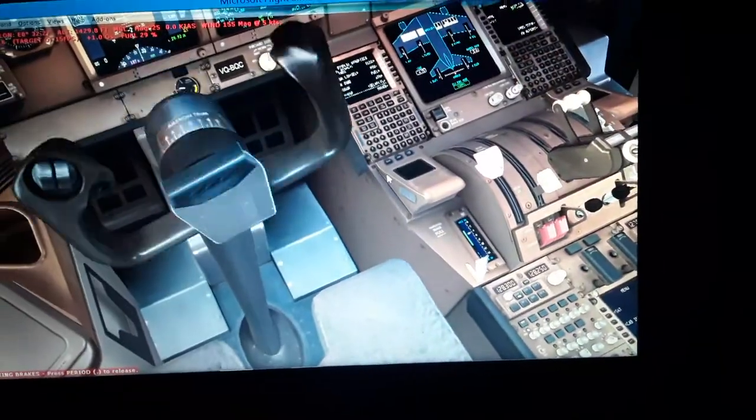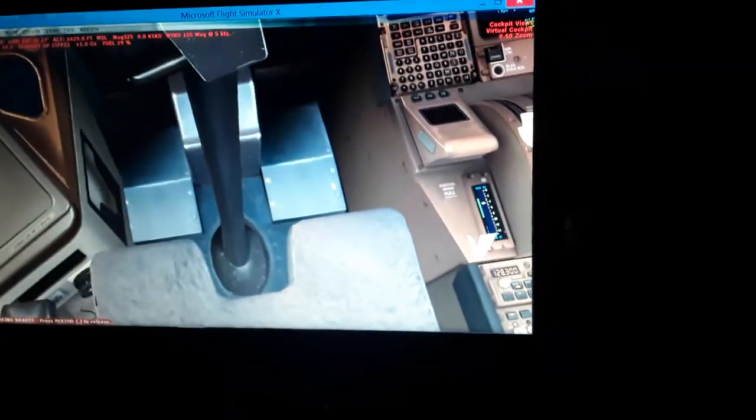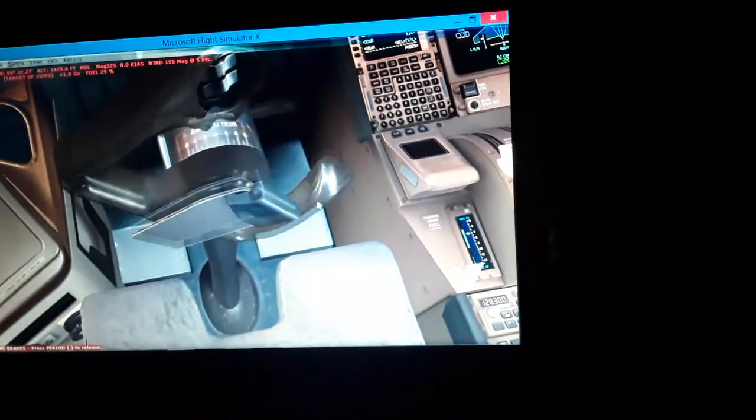So you can see we pitch up and pitch down the aircraft using the horizontal stabilizer elevator section. We also use the pitch trim of the horizontal stabilizer, which balances the aircraft using its aerodynamic forces from the tail, the horizontal tail of the aircraft as we fly. So you can see here pitch up and pitch down using the elevator and bank roll using the ailerons and the spoilers.